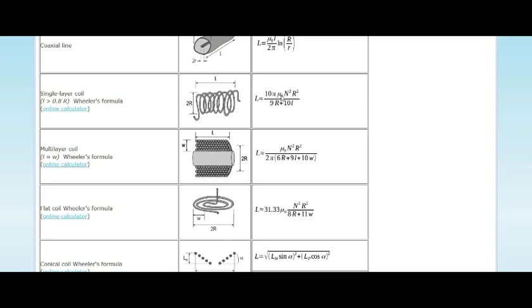The u0 is the number for the magnetic permeability of air. So if you have an actual core of like ferrite or something, then you've got to add in what the relative permeability is of the material as well. N is your number of turns, R is your radius, L is your length. And so that's what you have here.